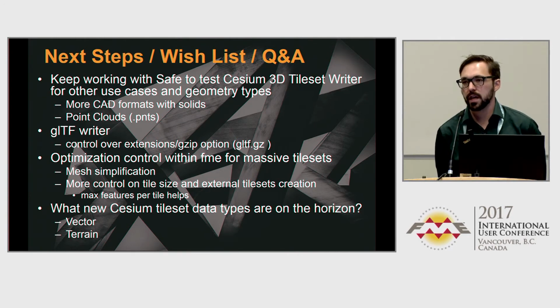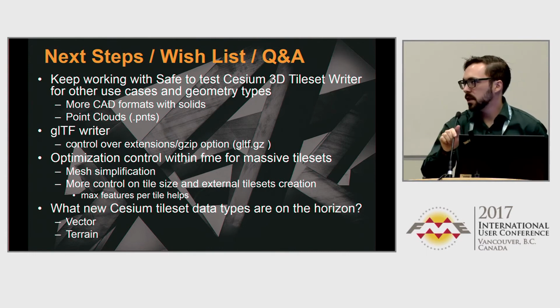What we were finding with the old KML way was we were trying to shove in 500 megs of tiles and just leave them all in there. And actually the GPU RAM would completely fill up, and the reason it would go orange was because the OS just couldn't fit in there anymore. Even the OS couldn't render. But with the 3D Tiles spec and the way it's all chunked, stuff will come back out of memory, and the renderer is smart enough to know when something's important and when it's not.